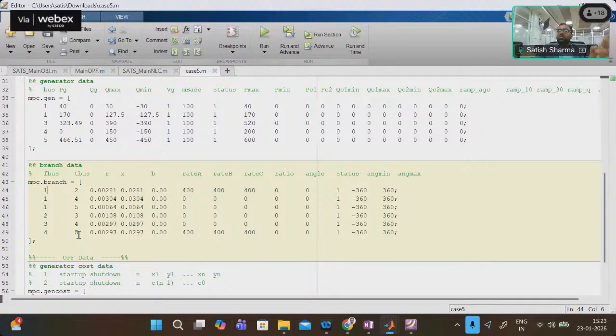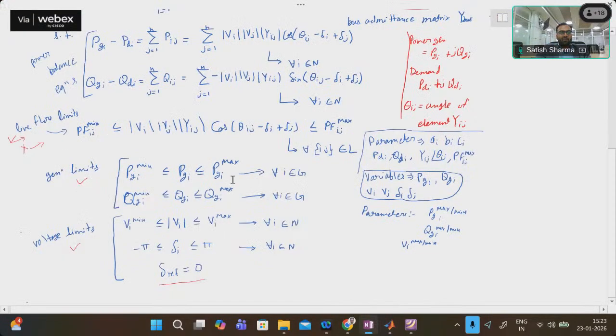So I will check it for both columns. If 1 is written here instead of here, still a line is connected to bus 1, so there is certain power flow. So I have to write down that Pij for that particular line as well, right? Pij will be given for all the lines, whether it is in from or in to. So it should not make any difference.